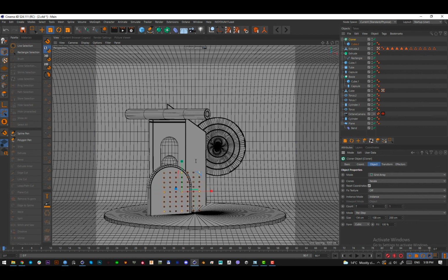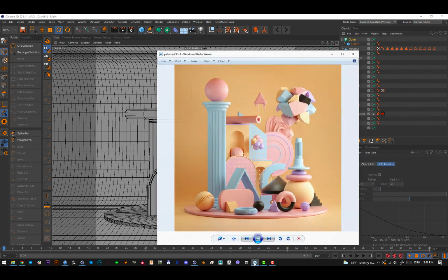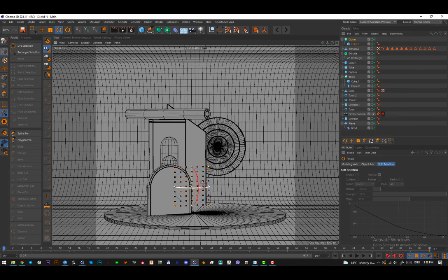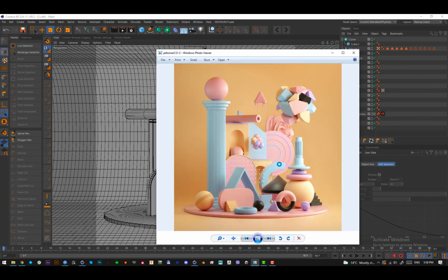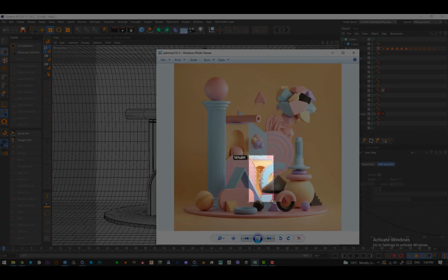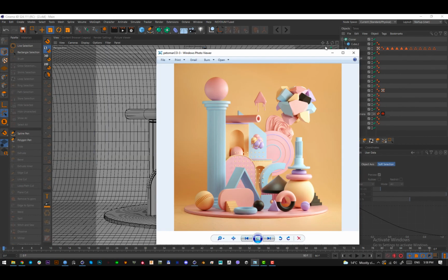And increase it like this, and put that cloner somewhere here. Okay, this is fine. Select the cube again and scale it down a bit by pressing T. Okay, this element is done. Let's now create another one. Let's see this one here. It looks pretty similar to this, so let's just duplicate that element.